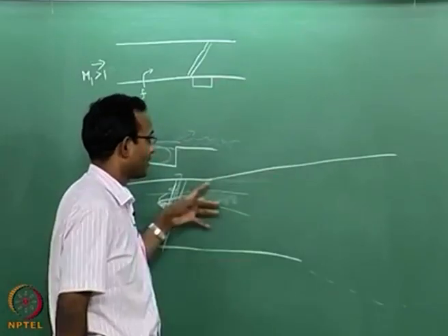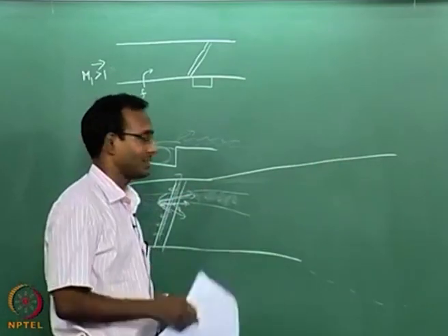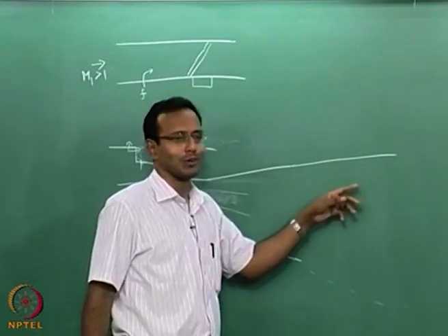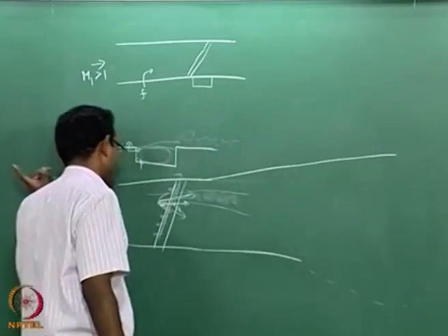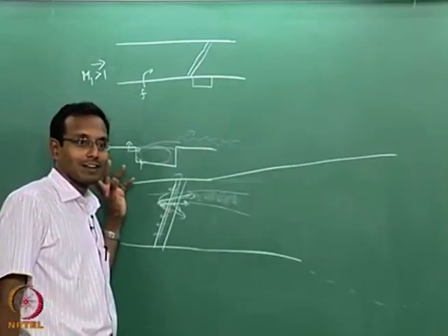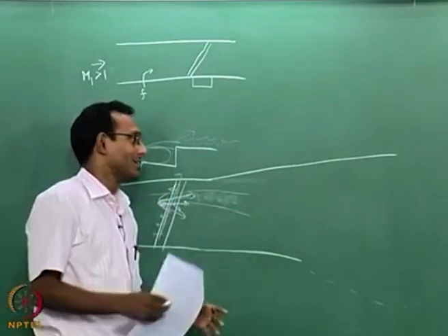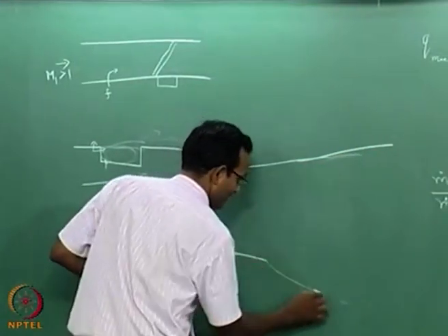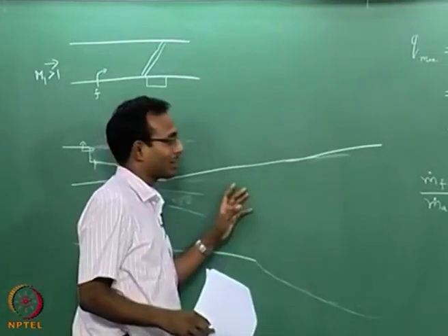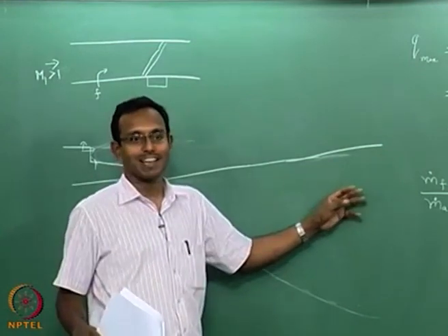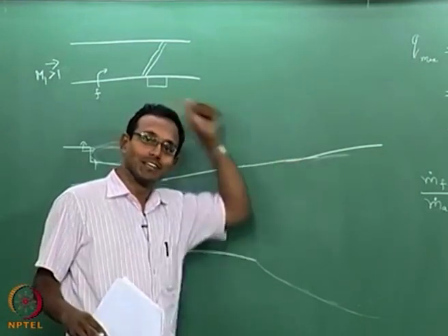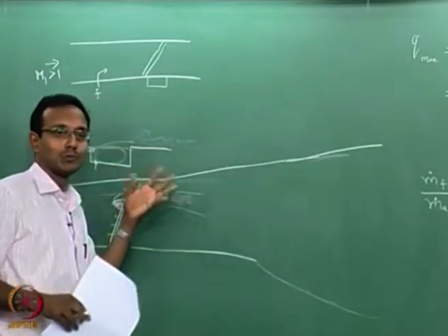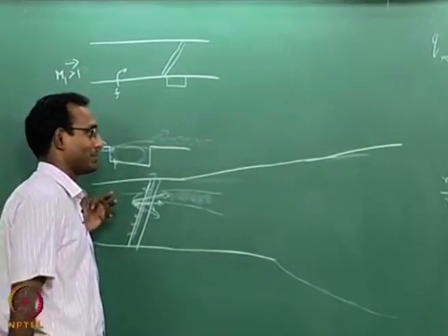Okay. Before that it has to finish all the job, that is the idea. And of course I do not want it to be exiting at M equal to 1 because I am flying supersonic, it is a scramjet. I do not want it to be exiting at M equal to 1. I have to think about having a nozzle here and a free expansion on this side to make the Mach number slightly higher than or equal to the incoming Mach number. That is what I am thinking about. I want it as close to the incoming Mach number as possible. I want to think about all that.